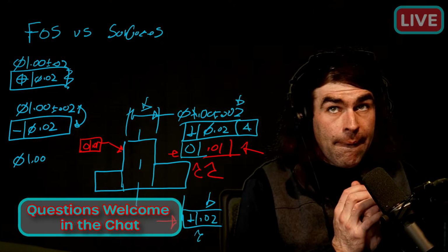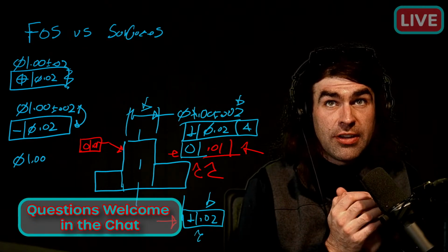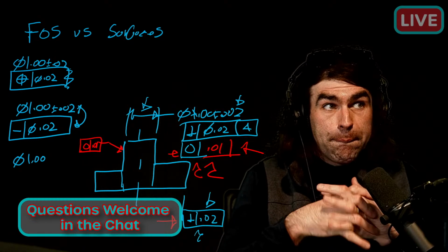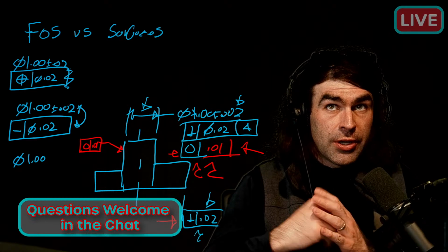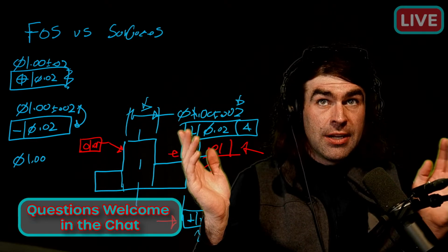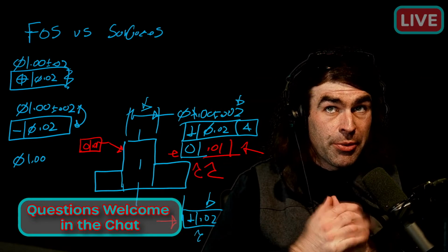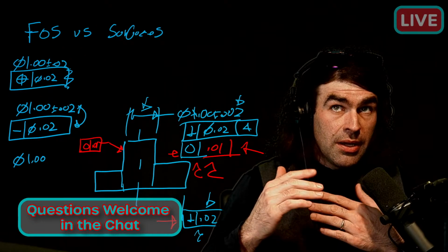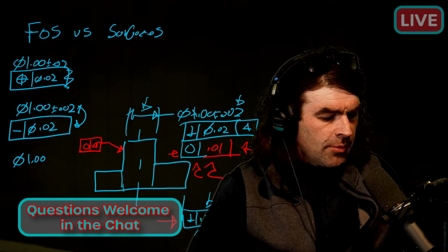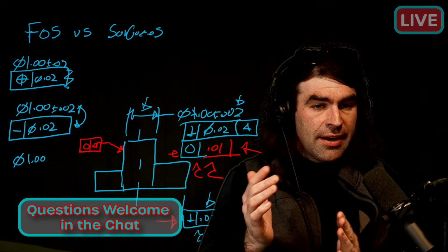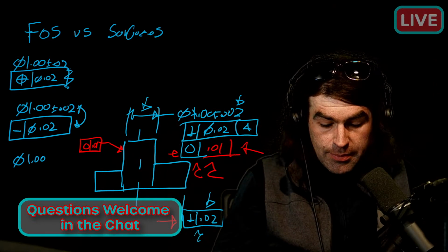But yeah, with runout, I think it's still allowed, but it's not recommended to put it with the dimension for this reason that I've kind of outlaid here. With a runout, you're controlling the feature of size, but you're controlling the surface of it. So you can achieve coaxiality. It's not like cylindricity where it's totally unconstrained, but you're directly controlling the surface. So in that way, it's very similar to profile if you constrained it to the datum axis. So hopefully that answered your question. That's a great question. And ASME, over the years, I think, is trying to get away from putting feature control frames with surfaces.